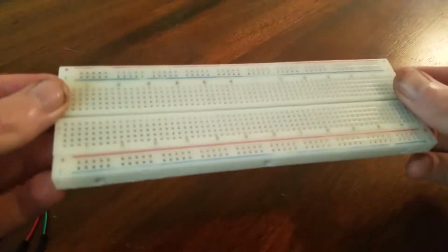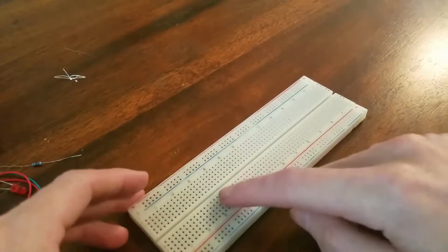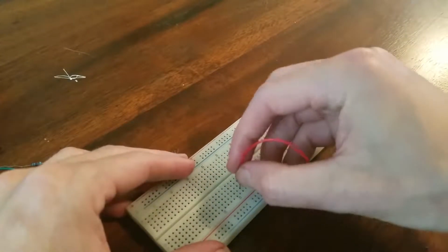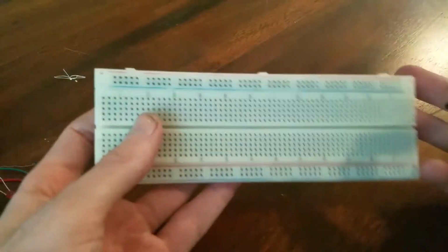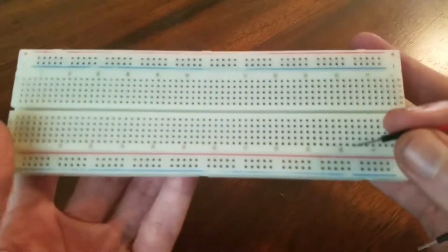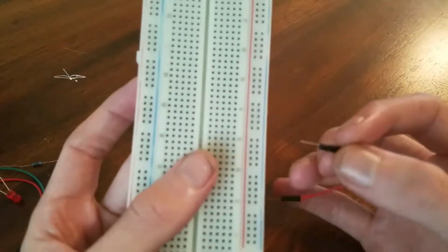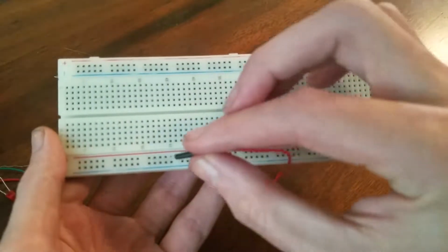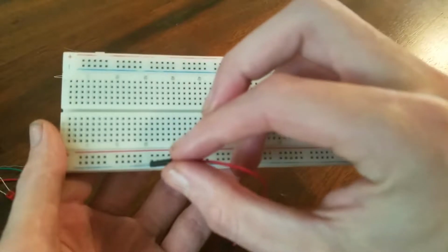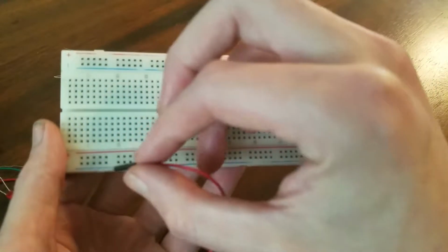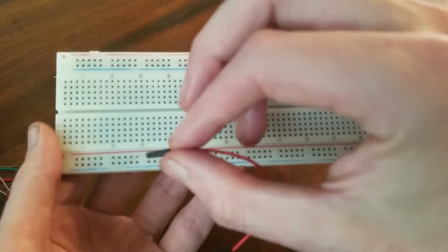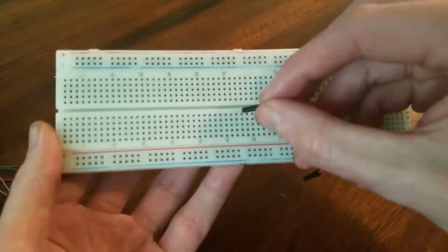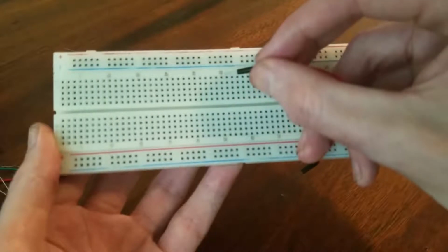A little bit about a breadboard. A breadboard is something that is used for prototyping. It is composed of a series of holes that you can plug a wire into like this. Underneath it is conductive metal. It's arranged like this. These holes down here at the bottom along this row are connected, but not connected to the blue right here. So all the blues are connected and all the reds are connected. And then in the middle, the connection goes up like this, breaks in the middle, and then up like this.